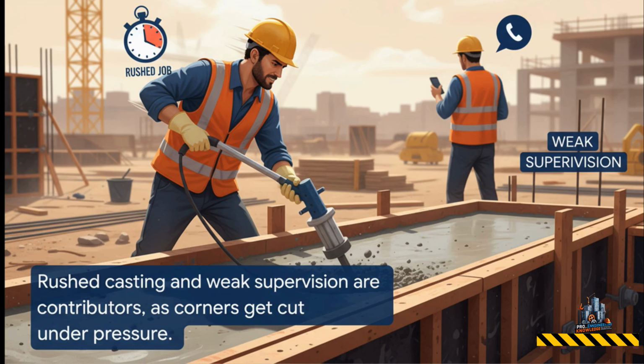And of course, good technique is often the first thing to go when you're under pressure. When a job site is rushed or when there's not enough supervision, people start cutting corners. Maybe they don't vibrate the concrete long enough, or they add extra water to the mix to make it flow easier. And those shortcuts lead directly to the defects we've been talking about. The people and the process, they are absolutely huge factors.